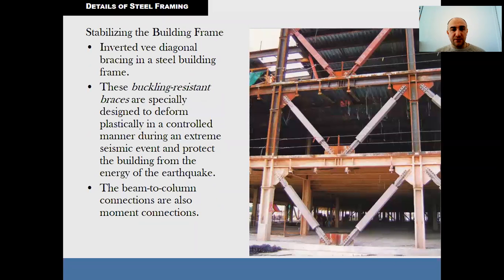And the last for today is the buckling restrained brace, BRB. It is a structural brace in the building designed to allow the building to withstand cyclical lateral loads, typically earthquake loads. It consists of a slender steel core and a concrete casing designed to continuously support the core and prevent buckling under axial compression.